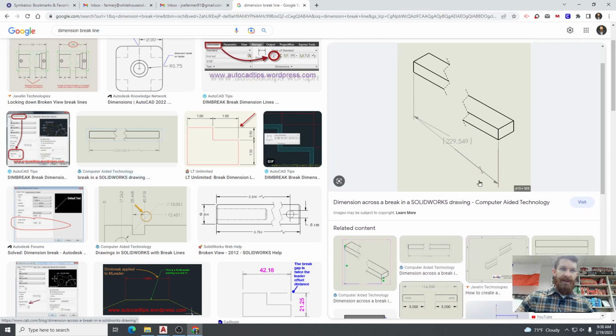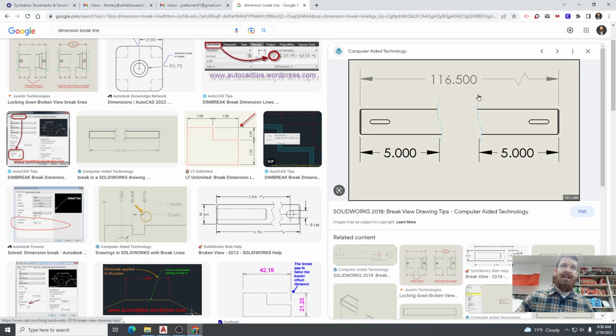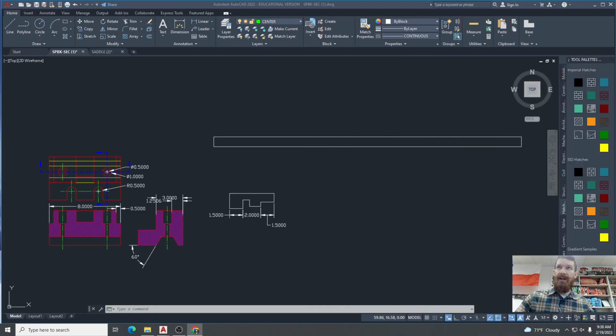There's another example right there in isometric view. Or something like this. This is 116 inches long, so they put a little dimension jog line in there. Very good. That is dim jog line. There's dimension jogged, which is basically the same thing that we just talked about, except it's for a radius or a diameter. For an extremely large radius, it may not be possible or practical to create a dimension line, so you use the jogged radius dimension line, which is the same thing we just talked about, except it's a radius, right?